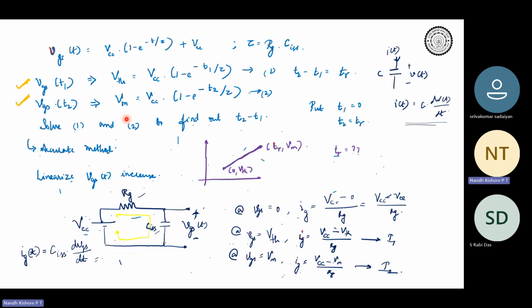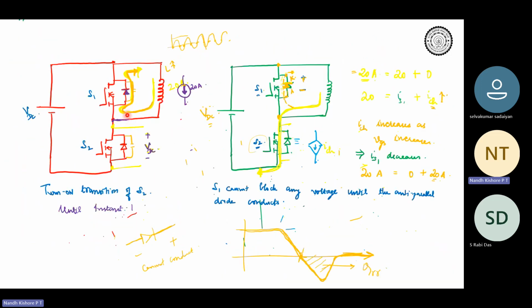There are two more aspects to it. One is obviously that there is the antiparallel diode that was conducting previously. Now the antiparallel diode stops conducting. So after all, it is just a diode, so the diode would be having its reverse recovery. As the diode current falls, it will not directly go down to zero and stay at zero. It will be having a reverse recovery, corresponding to the reverse recovery charge QRR and the peak reverse recovery current, and there would be a reverse recovery time.